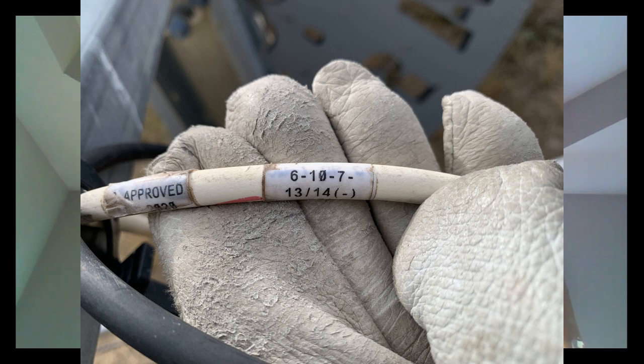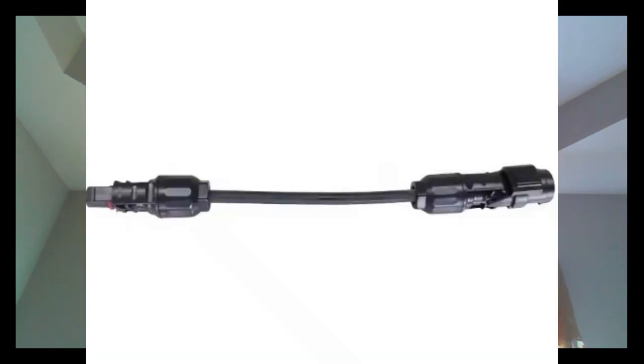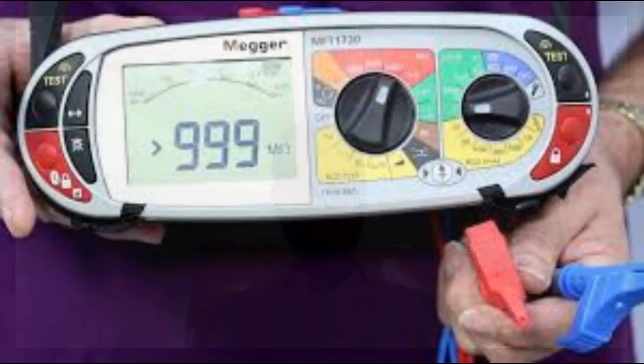Cut the conductor and remove any damage. Place a positive connector on one side and a negative connector on the other. Plug in the connectors, ensuring that they are all firmly in place. Repeat voltage and/or insulation resistance testing on the circuit to verify the repair.